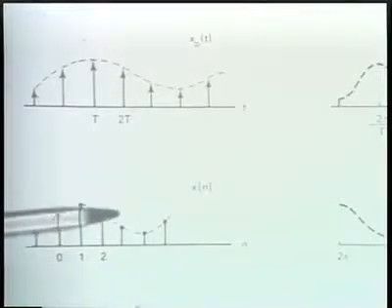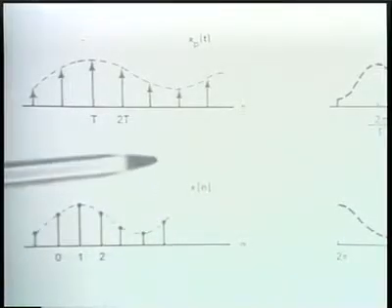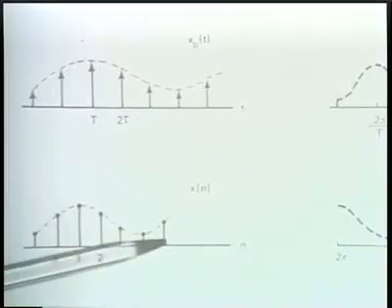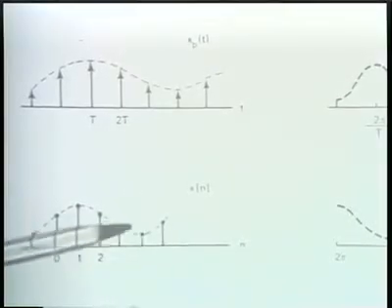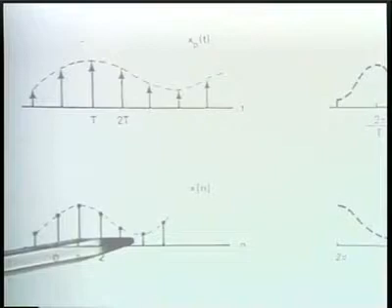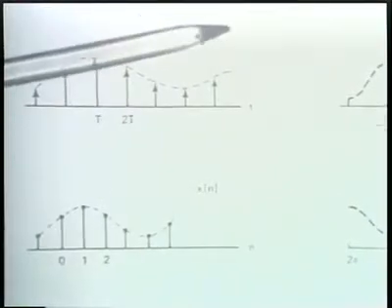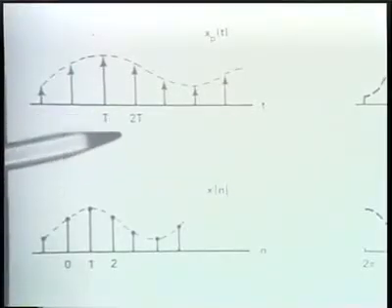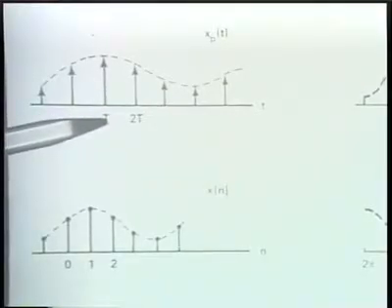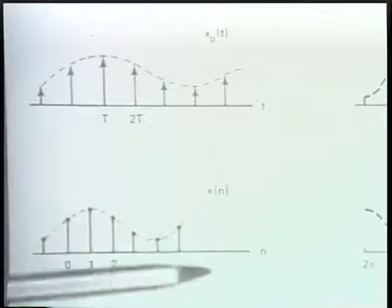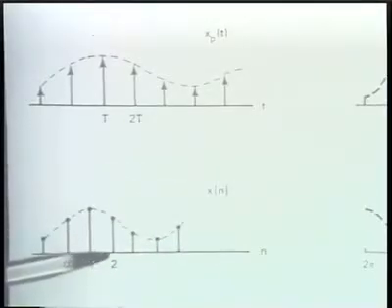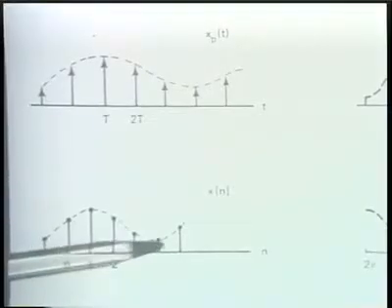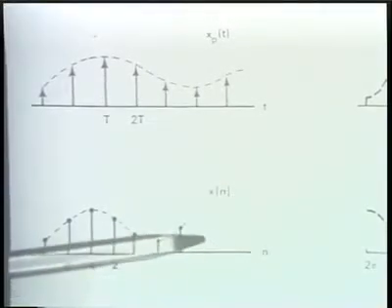And essentially, I'm now replacing the impulse by the designation of a sequence value. That's one step. But the other important step to focus on is that whereas in the impulse train, these impulses are spaced by integer multiples of the sampling period capital T, in the sequence, of course, because of the way that we label sequences, these are always spaced by simply integer multiples of 1.